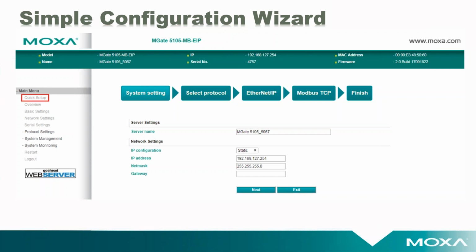The other thing, though, is that you can monitor that communication. You can take advantage of those error codes, right? So maybe you configured the device incorrectly, and now you're able to tell that a lot quicker, and you can diagnose it. You can export the logs and have somebody review them. If you wanted to troubleshoot a specific Modbus protocol that might be giving you issues, you can export those logs and review them as well. So it's a really great configuration wizard, super easy to use, with a lot of accessible information, and you don't need to be an IT expert to use it.